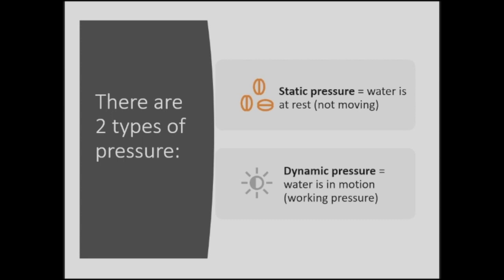Elevation, number one, right? So when we think about a water tank, it's going to create pressure from gravity, right? If that elevation changes, then the pressure is going to change. What's another way? Pump. Yeah. Yep. Time. What is it? Peak demand time. Very true. So, kind of like Charles was saying earlier, pressure changes throughout the day depending on what type of system you're running, what kind of water source you have. So, static pressure, elevation, and pump are basically the ways that static pressure can change.